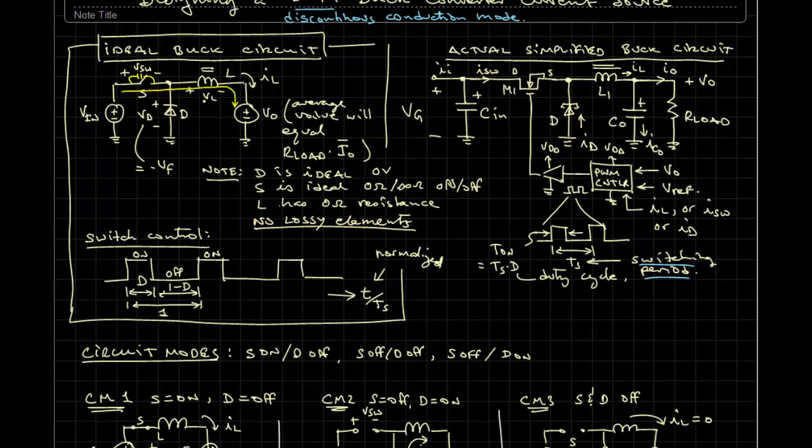The inductive nature of the inductor will cause the current to continue flowing. Actually, what will happen is the current will not change until VL changes, and VL cannot change until the voltage across the switch rises. But for it to rise, imagine if there's some capacitance there, it's going to take a little bit of time, albeit maybe nanoseconds, for that voltage to rise.